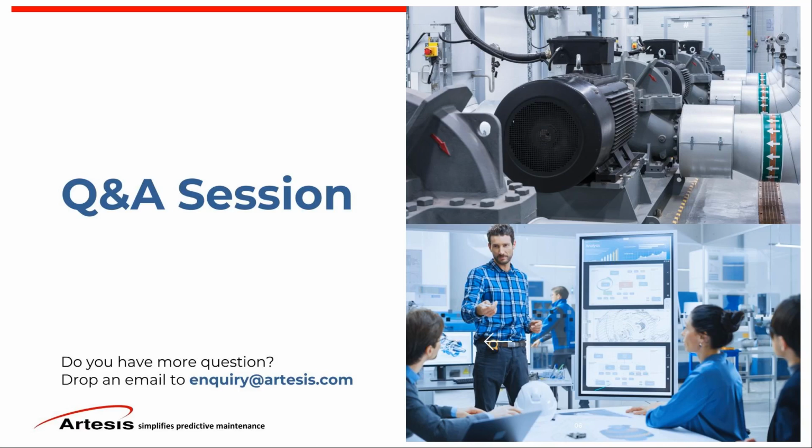So the mechanical fault detection, this was a question from Rami. Basically, each type of mechanical fault will distort the air gap between the rotor and stator, so that will translate into fault frequencies in the current waveform, and that's how we are able to detect mechanical faults. Recording will be available.